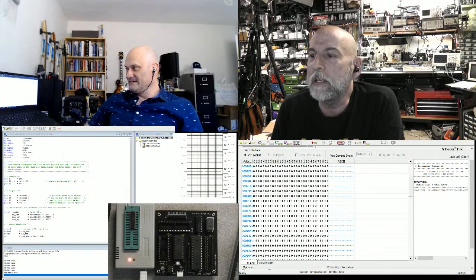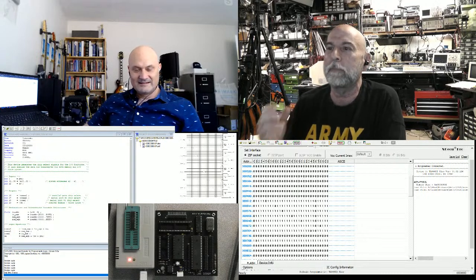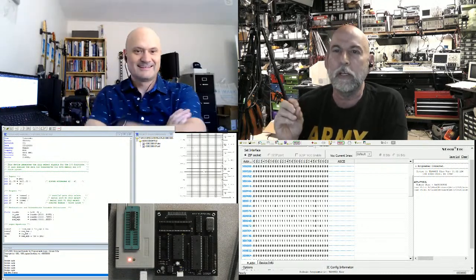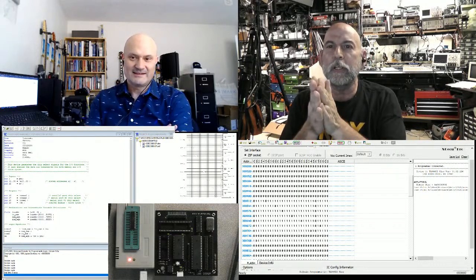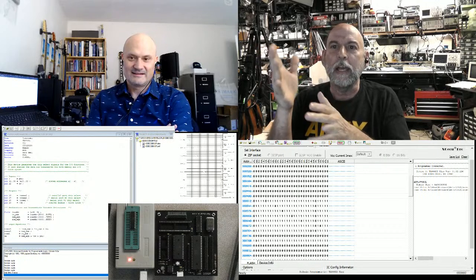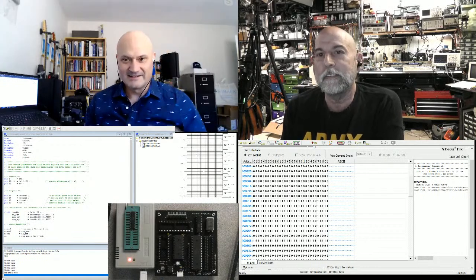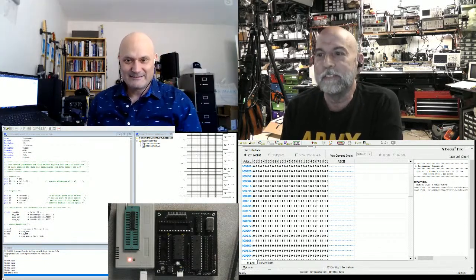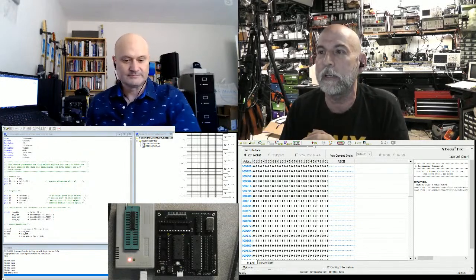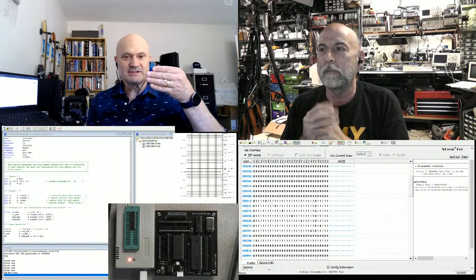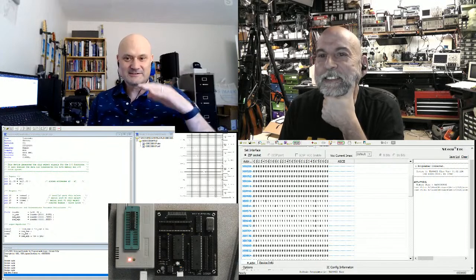But in a small computer, there's always one function that a PLD just screams to be put in, and that is the address decode. An address decode quite simply looks at the address coming out of the processor, which is a binary number, an unsigned integer, which I visualize as hex. We almost always knock it into hex, because each digit is a nibble, so it's neat and tidy.